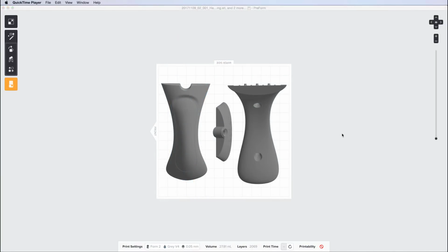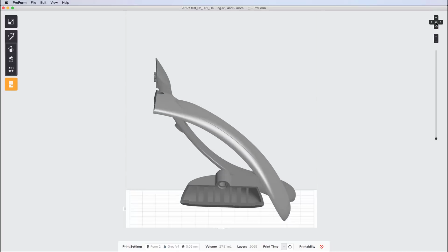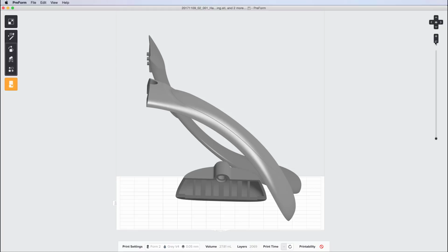If we now look at the parts in plan view, this is an example of how we might position the parts to optimize printing. There's a good amount of room around each of the parts, and this will propagate a good resin flow. If we look at an elevational view, you'll now see that all of the supports that need to be generated will be connected to the B surface of the product, and that the longest or tallest supports are on the wiper side of the printer. This is important and helps the build of those tall supports.